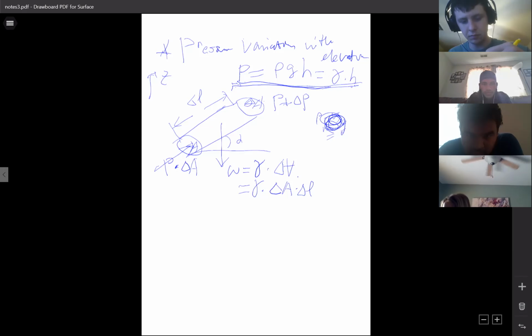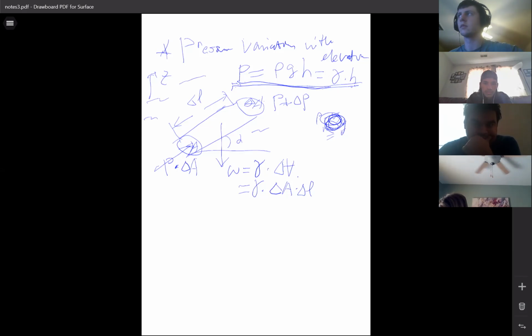On this element in the free body diagram, you need to get all the forces. You will say, hey, why do you have force? This is actually because you detach it. It's infinitely small, but you still detach this fluid element from other elements, right? This is the fluid element. It's inside the stationary fluid, right? You detach it, actually there's a force on the surface, right? So that's a pressure force, okay?